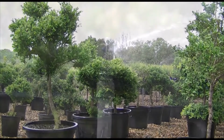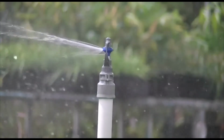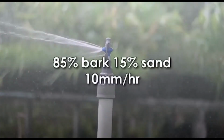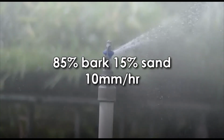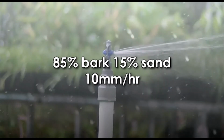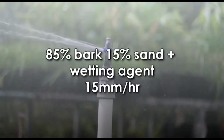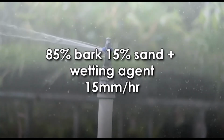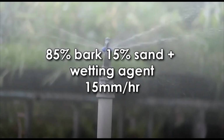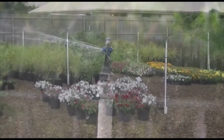media components. Some growing media absorption rate examples are a growing media consisting of 85% bark and 15% sand would have an absorption rate of approximately 10 mm per hour. A growing media consisting of 85% bark, 15% sand, plus a wetting agent would have an absorption rate of approximately 15 mm per hour.